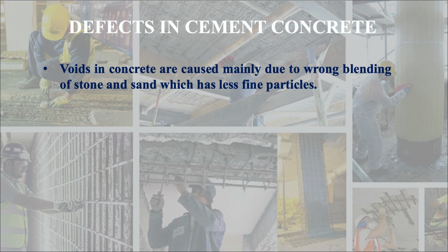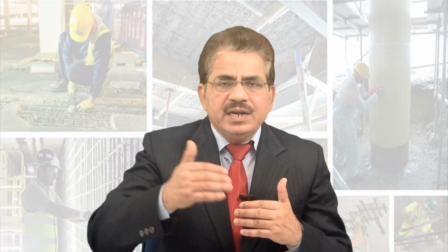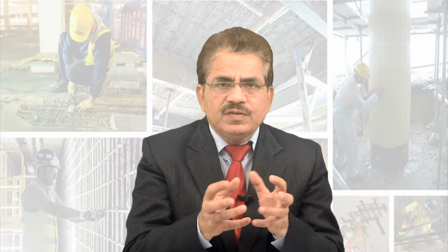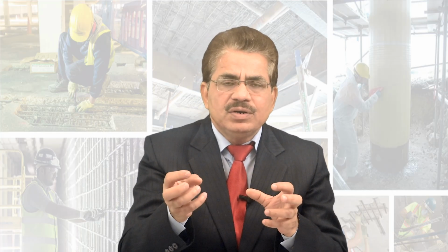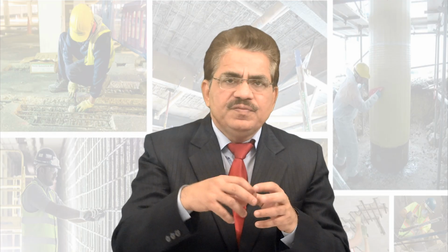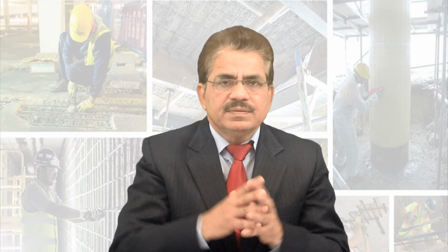Voids in concrete are caused mainly due to wrong blending of stone and sand, which has fewer fine particles. If fine particles are fewer, then voids will be there in the concrete, because the voids of the coarser particles are not filled if fine particles are missing.